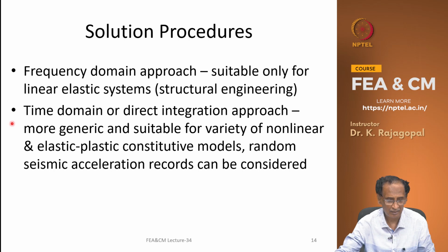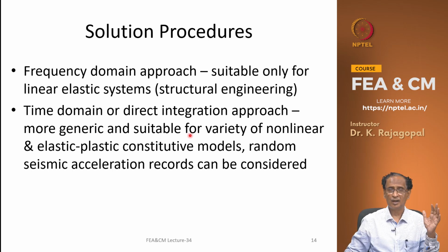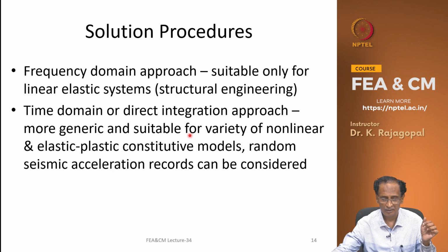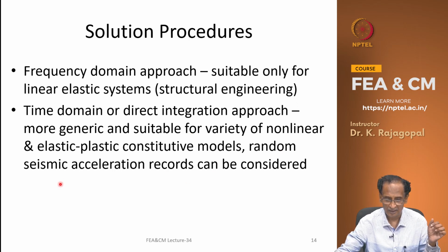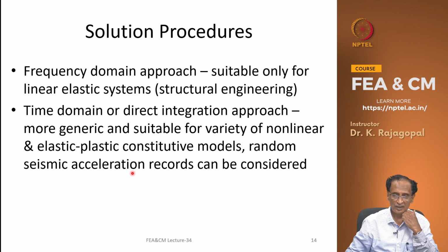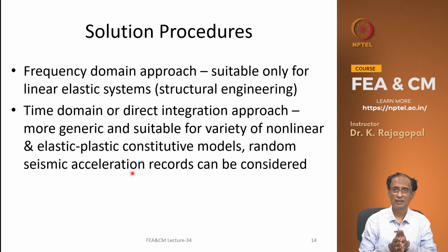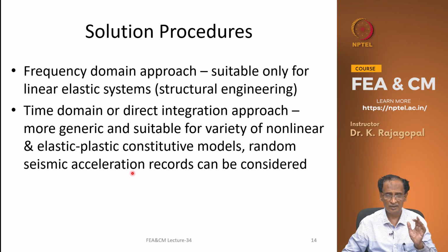Then there is another method called the time domain method or the direct integration approach, and this is more generic and suitable for any type of nonlinear problems or viscoplastic, viscoelastic or elastic plastic and so on. And we can also include the response under random seismic loading and so on, whereas the frequency domain approach is good, but it is only valid for some simple problems.